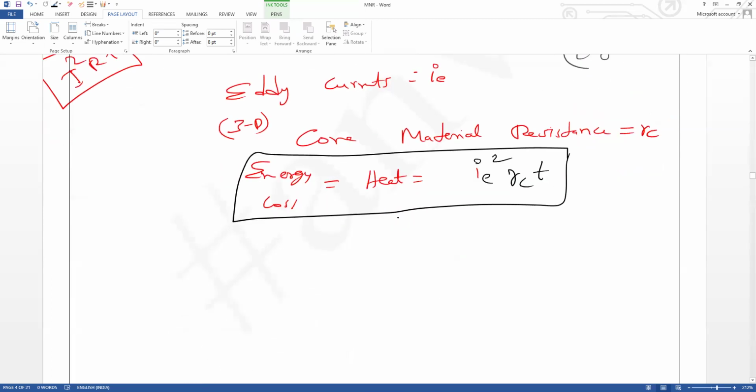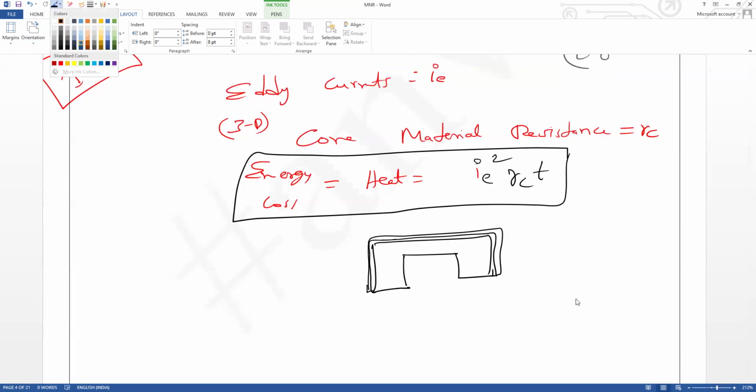To minimize this, we are not going to put a big 3D iron core. We are going to use plates. You might all remember plates. So laminated core plates, one plate behind another plate, one after another. Imagine it in three dimensions. In between the plates we will use some insulating layer so that it reduces the size of the eddy loops. So it will become two-dimensional plates now, area. Before it was volume, now it will turn into a single plate. So we are going to use...